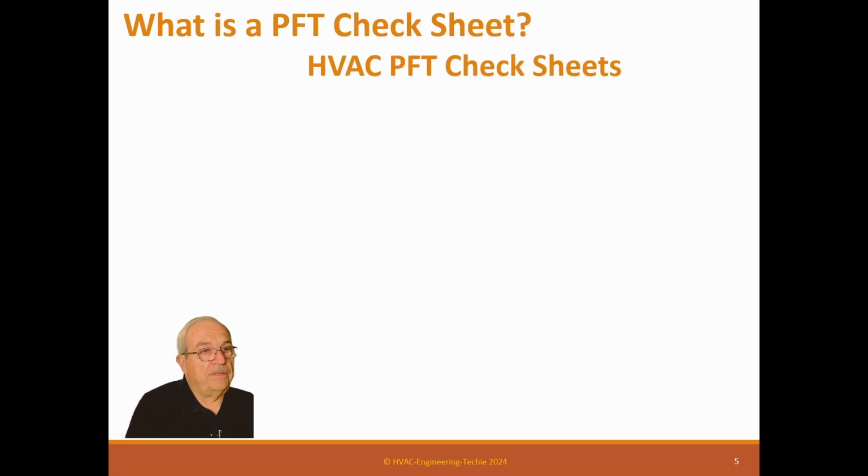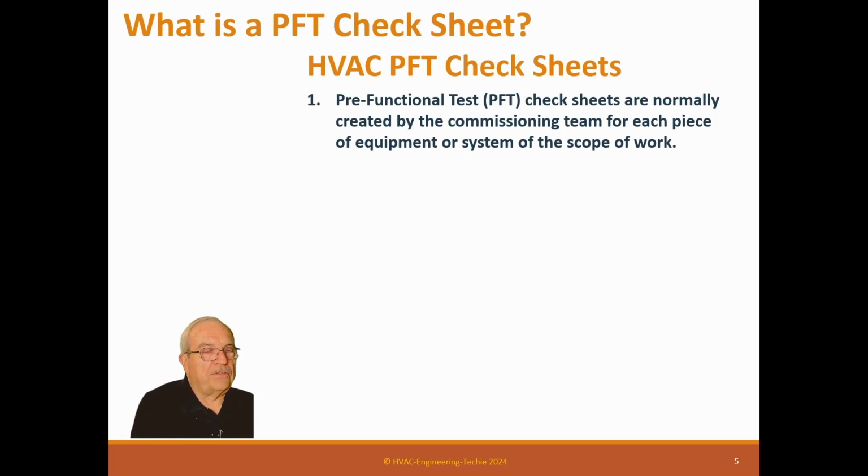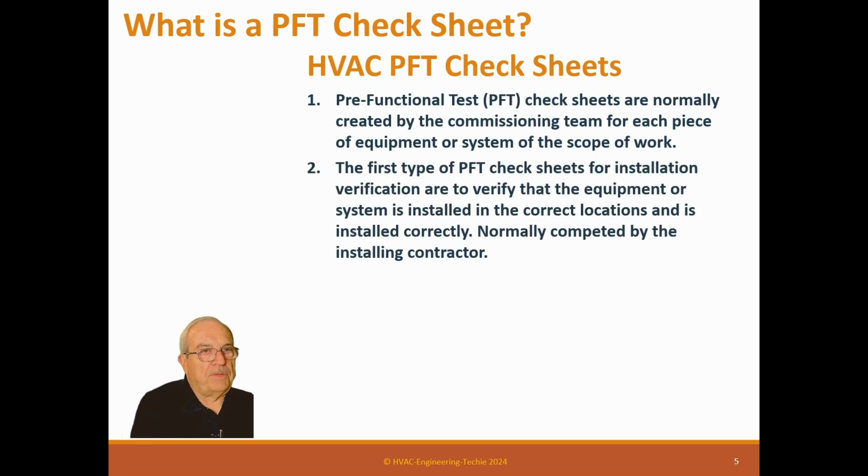What is a PFT check sheet? HVAC check sheets, the pre-functional test check sheets, are normally created by the commissioning team for each piece of equipment or system of the scope of work. The first type of PFT check sheets, for installation verification, are to verify that the equipment or system is installed in the correct location and is installed correctly, normally completed by the installing contractor.